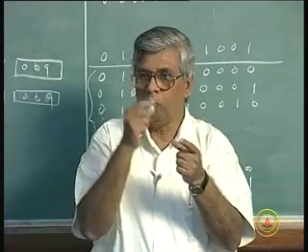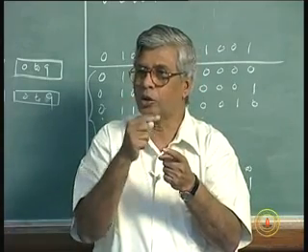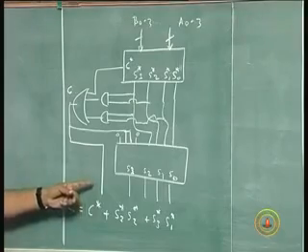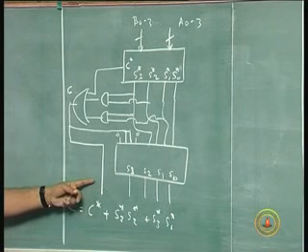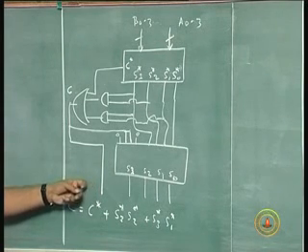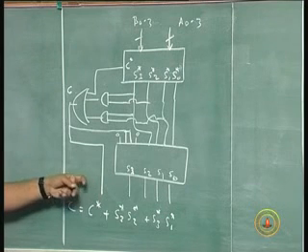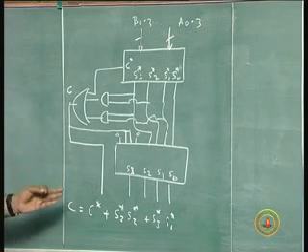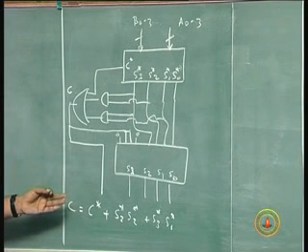So whenever I add 6, I also should get my extra digit. This is that extra digit I was talking about, which can be 0 or 1. If it is a 0, the number is less than 9, 1 if the number is greater than 10. 10 to 19, this will be 1, 0 to 9 will be 0. That is what I meant by putting a simple LED to show whether this number is less than 9 or greater than 9.